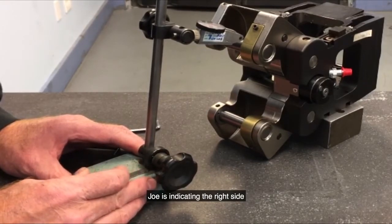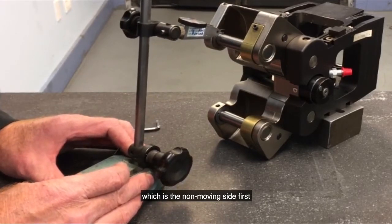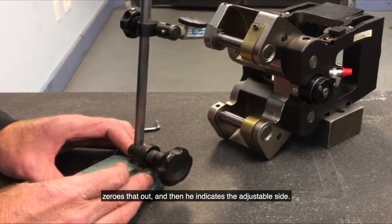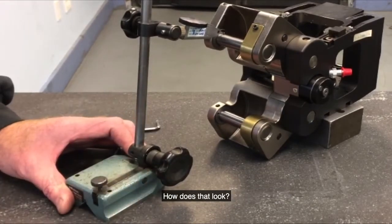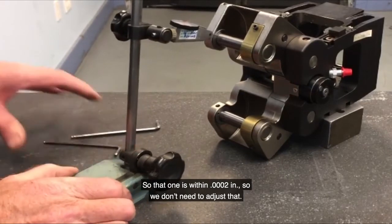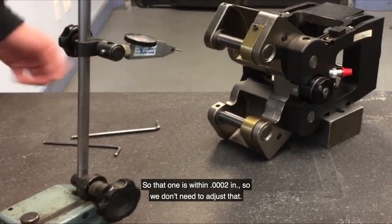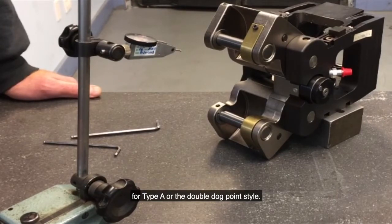Joe's indicating the right side, which is the non-moving side, first, and zeroes that out, and then he indicates the adjustable side. And how does that look? This one is within 2/10, so we don't need to adjust that. And that's how you do the taper setting adjustments on a pneumatic attachment for Type A or the double dog point style.